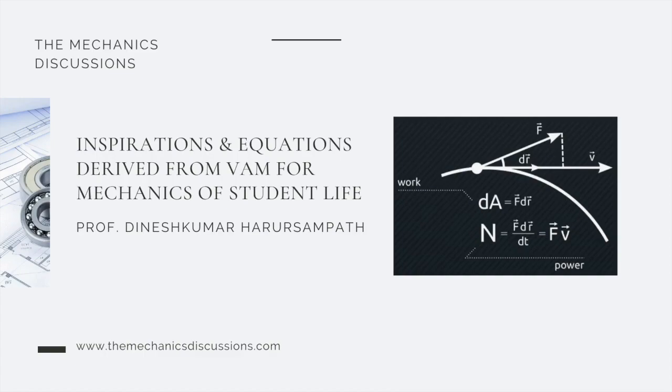That's where, as opposed to a regular variational principle, the variational asymptotic method works much more brilliantly, because with these approximations you can take into account the small parameters involved, not only with the geometry but with the physics of the problem, in terms of how big or small the shear stresses of the fluid on a particular structure or between its own layers are compared to the pressure forces.